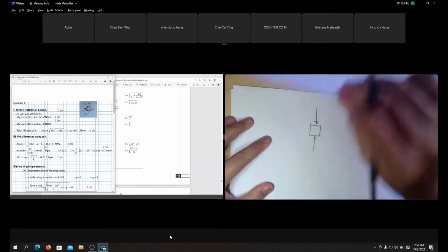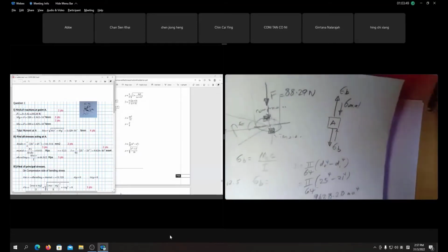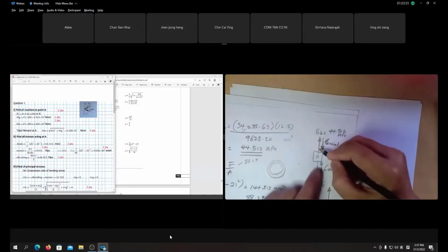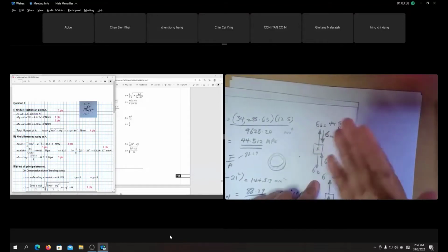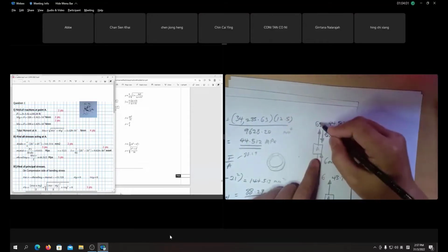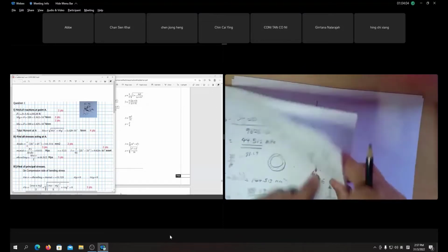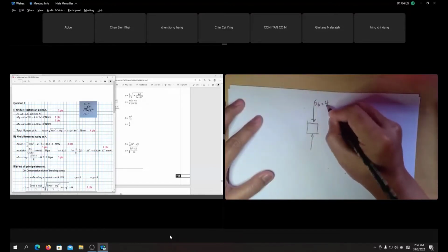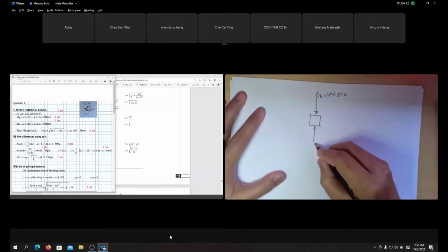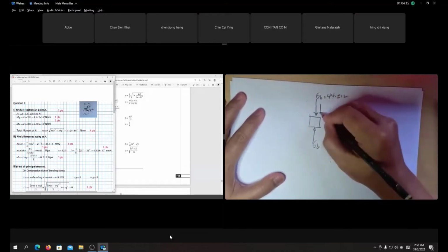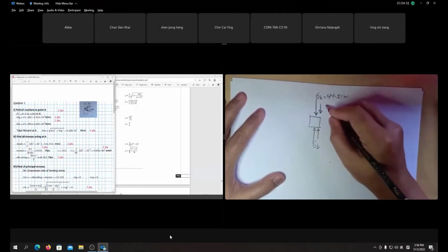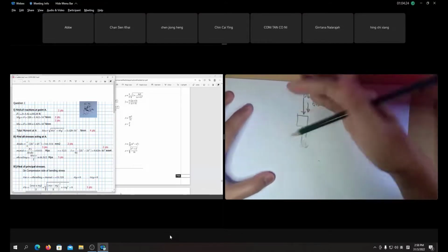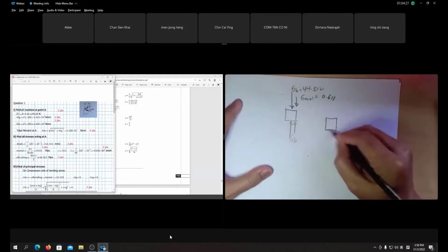So earlier we have total sigma, we already calculated, right? We already calculated that sigma bending earlier is 44.512. This one we go tension because it is up. But on the other side of the neutral axis, compression mode. So sigma bending goes downward. So 44.512 is downward, because we go for the compression side. Plus that, we have sigma axial earlier, also downward, right? Sigma axial earlier was how much? 0.611. So we add it up. Can you see? So the element at A is critical at the compression side.